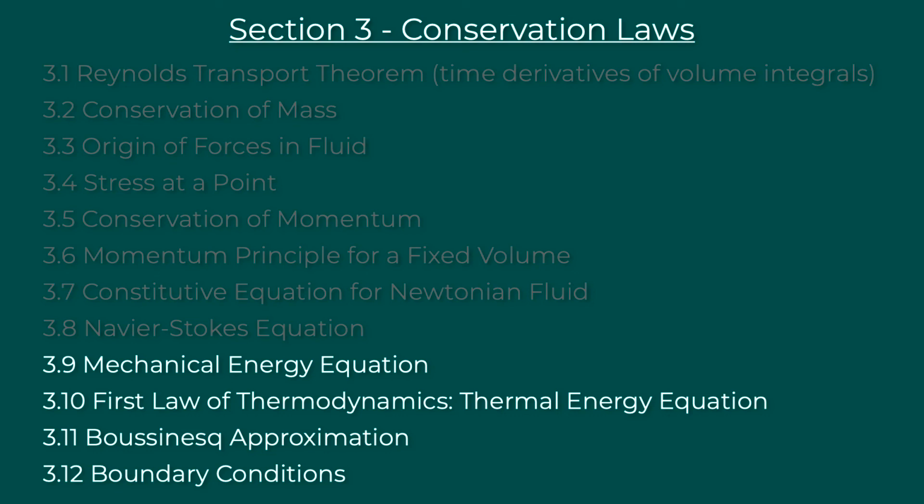We would be able to solve for like temperature as well, whereas previously our mass balance and our momentum balance would help us solve for velocity and also pressure gradients, but now our energy equation can help us solve for temperature too. We looked at the Boussinesq approximation, which is a way of simplifying our equations that shows up somewhat commonly, so it's good to know what that means.